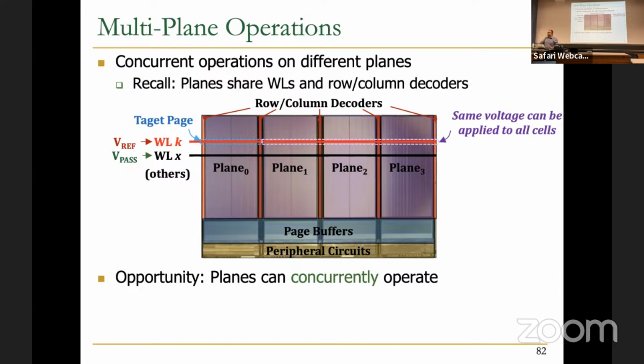Usually, when the application requests more than 64 kilobytes at a time, you consider it a sequential request. The application sends the request to the SSD, and then you make it into sub-requests and process it through the FTL. So that's what we consider sequential requests. But for random, you usually have 4 kilobyte, very small requests.